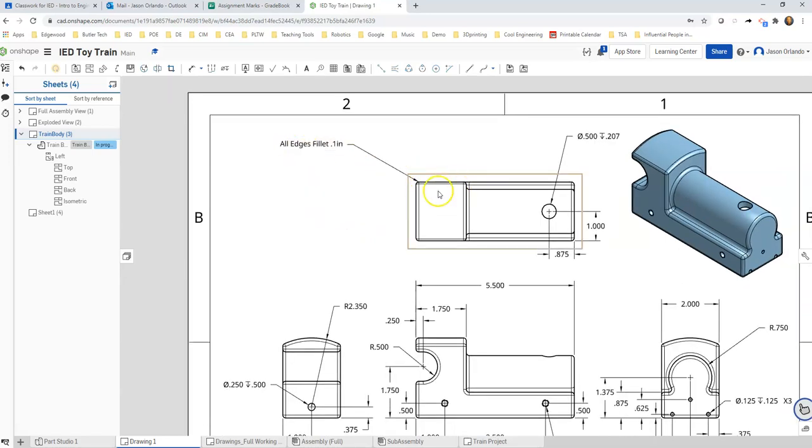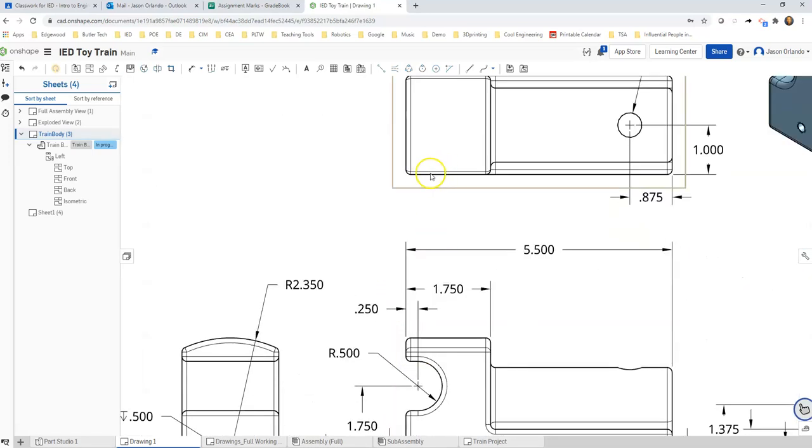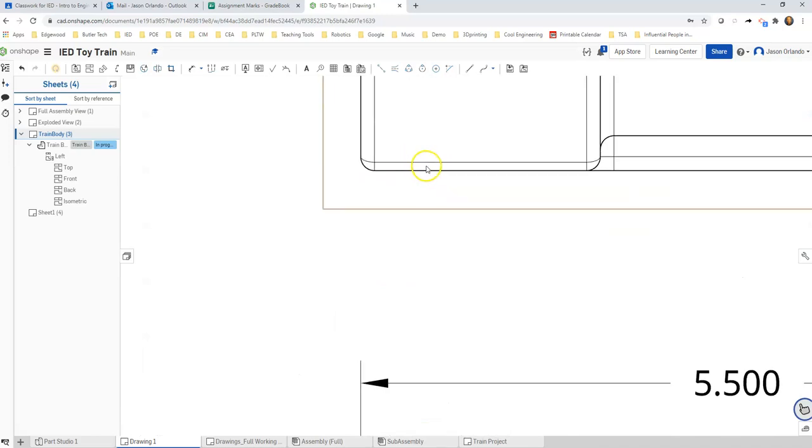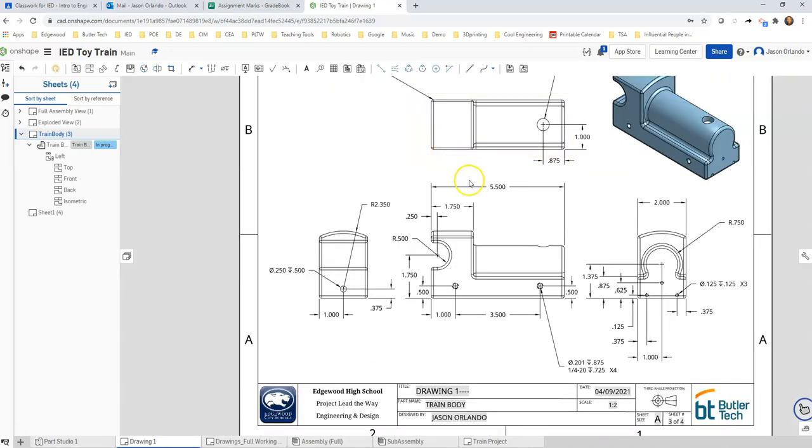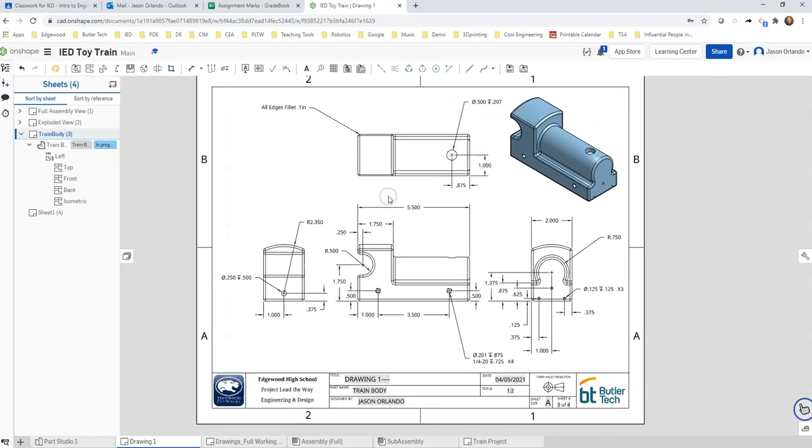That's just kind of pointing to a corner. You see all these kind of double edges, right? And that's because of kind of the overall dimension, but this is in this little region. That is where that fillet was taking place, that is rounding over, and this thin line is the transition from the curved area to the flat area. So I think that is fully dimensioned.